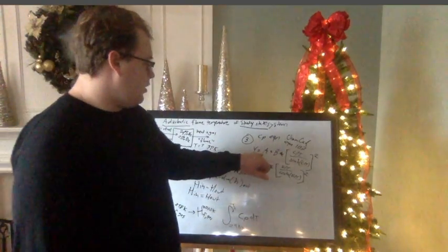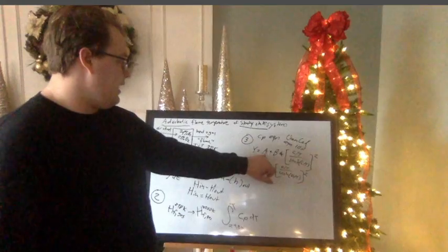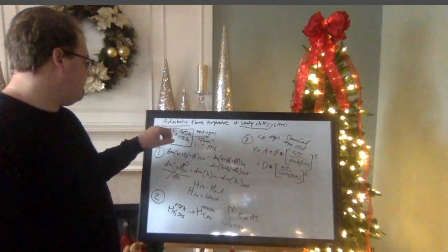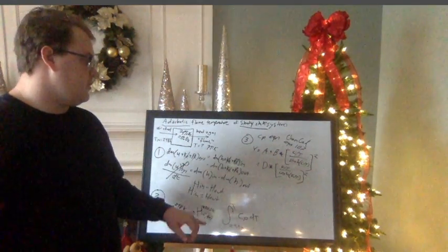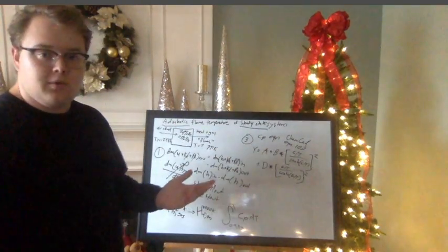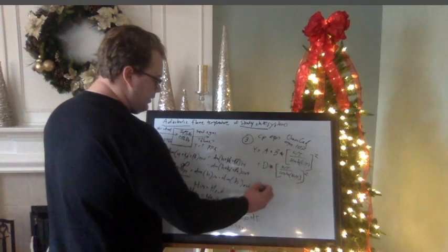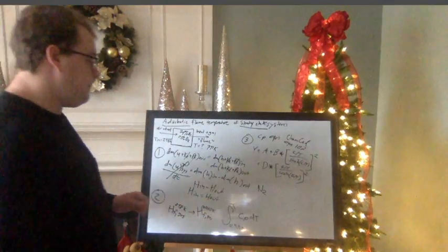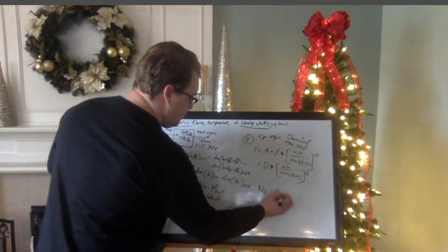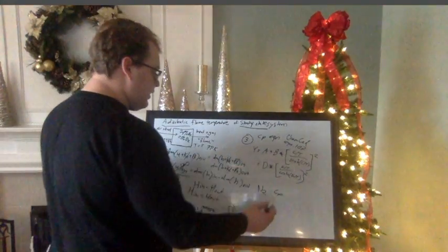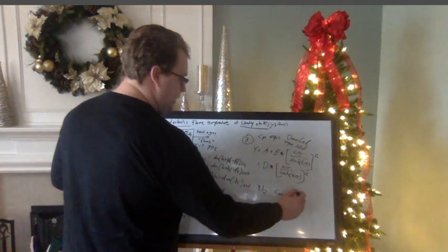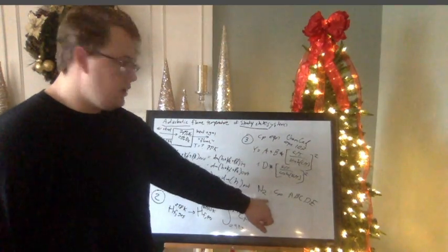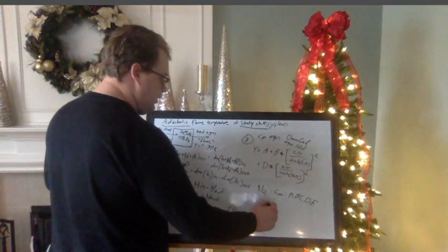So here we've set up our 5 different variables, A, B, C, D, and E, which all correspond to a specific compound, so air or our fuel, at varying temperatures. So, for example, let's say we have nitrogen, N2, which makes up most of our air that we're using as our inflow, 79%. So the specific heat of our nitrogen is going to be dependent on these variables, A, B, C, D, and E. These directly correspond to the specific heat of nitrogen as our temperature goes up or down.